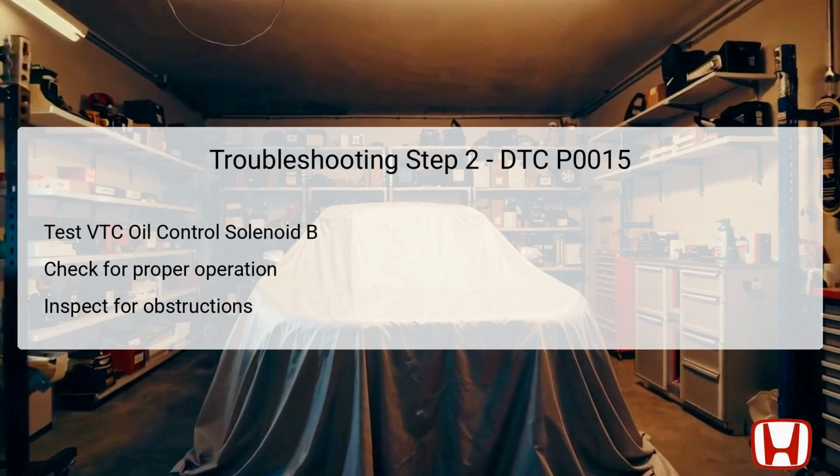Additionally, it's essential to inspect the solenoid for any obstructions or debris that could prevent proper oil flow. This examination also extends to the oil passages leading from the solenoid to the actuator, ensuring that any buildup is cleared to enable optimal performance.